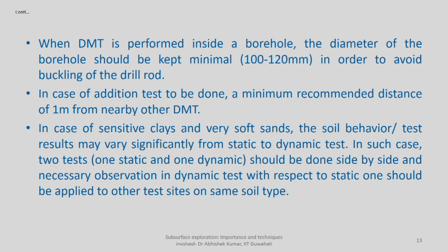Again, when the DMT is performed inside a borehole, the diameter of the borehole should be kept minimal in order to avoid any kind of buckling to the drill rod. In case an additional test is to be done, a minimum distance of 1 meter is recommended from the nearby test. So if your distance is more, that is fine. This is given as the guideline for minimum distance.